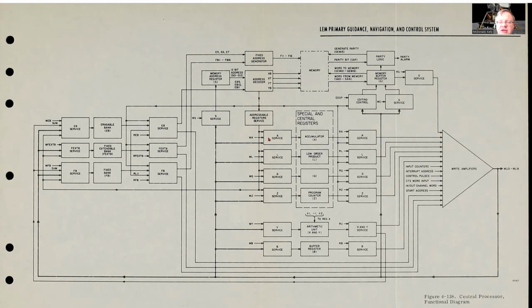Both on the input side and then on the output side. And this is just to implement certain logic around, for example, when do we write data into the accumulator? Here they've got a little WA signal, which is a write A. So that means, when do we want to input data into the accumulator? Well, there's going to be a signal pulse that's a WA signal pulse. And there's a few other conditions. We'll see those as we go through for each register.